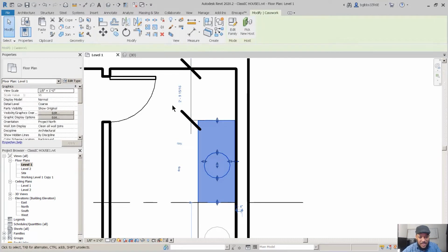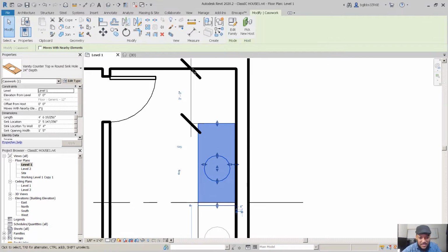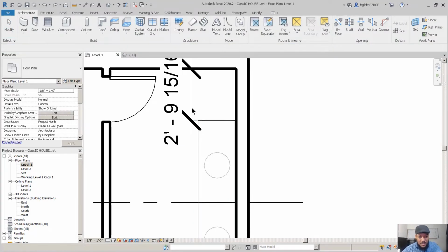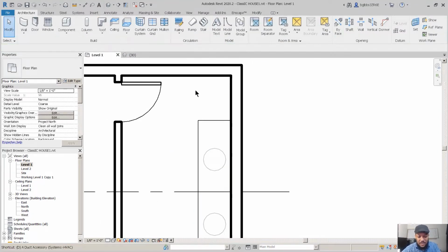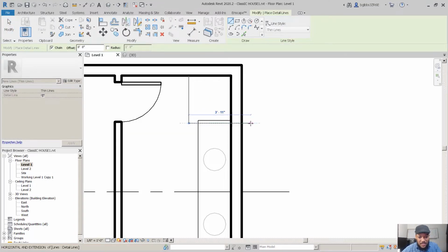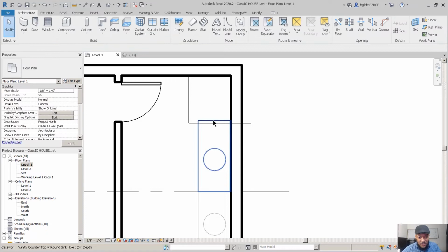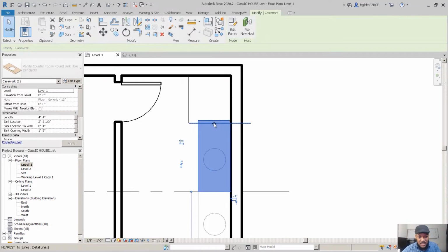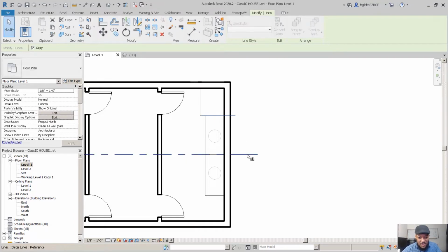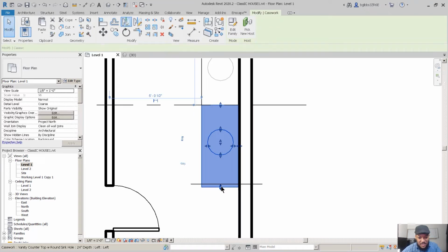We're going to make that placeholder 3 feet. I just move this over a little bit, and we'd rather just make a detail line to find out the information that we wanted, and we're just going to move this. So be careful with the line. A line has some good features and sometimes it's confusing. I'm going to mirror this, and we're going to change this now.